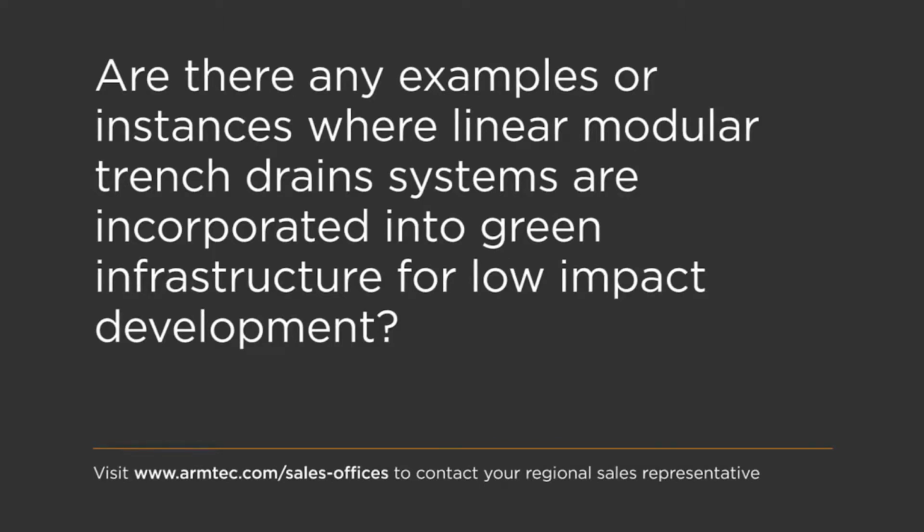that might refer to using a trench drain system as a water attenuation system, as a storage system, and again these systems are integrated into water attenuation systems. So what we can do is provide high capacity trench drain systems, and typically larger units are used, and the trench drain run will be a larger trench drain unit that can be used to store water. And you fit a flow regulator at the catch basin end to regulate the flow of water away from the trench drain.